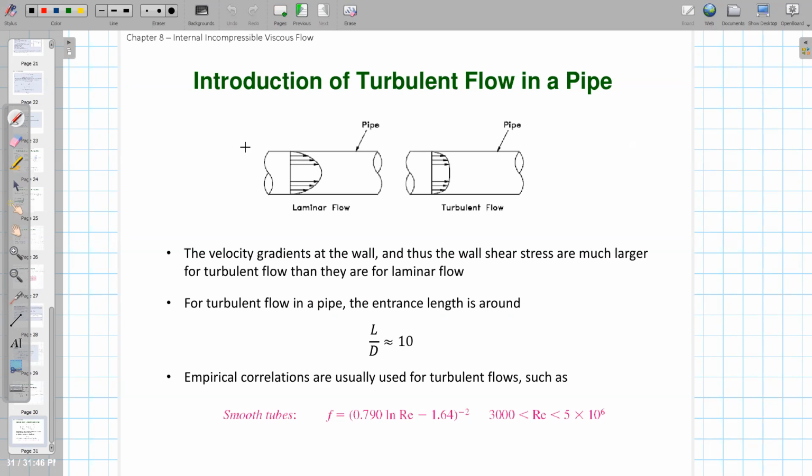Because the turbulent flow, as I introduced before, has some random behavior, which means statistical things, those probability functions, will be involved when you try to write the flow equations. So that makes the math very hard to solve. Another difficulty is that inside the turbulence we have small eddies, and they also, as a behavior, dissipate the kinetic energy, the flow energy, into thermal energy.